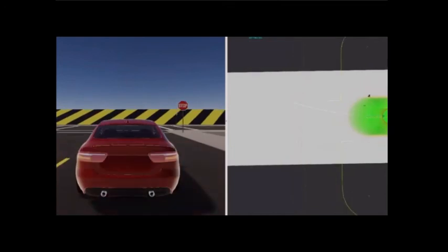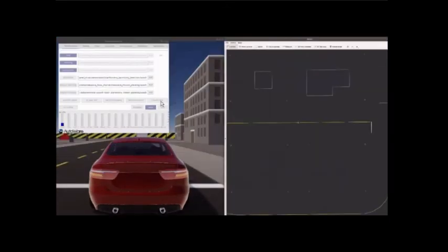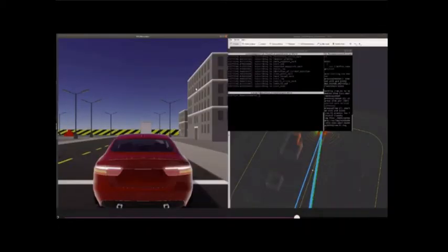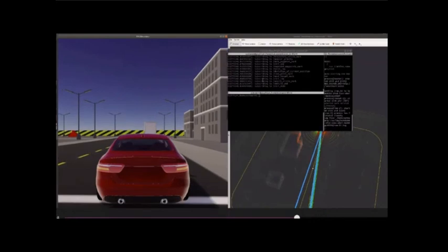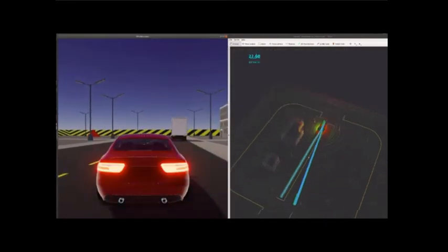And yes, as you can check, the threshold was different. One planner calculated that the goal point was a little bit ahead, at the crossing, the stop sign, the other before. And as I said, the first path planners didn't obey the HD map info. And this was the OpenPlanner.